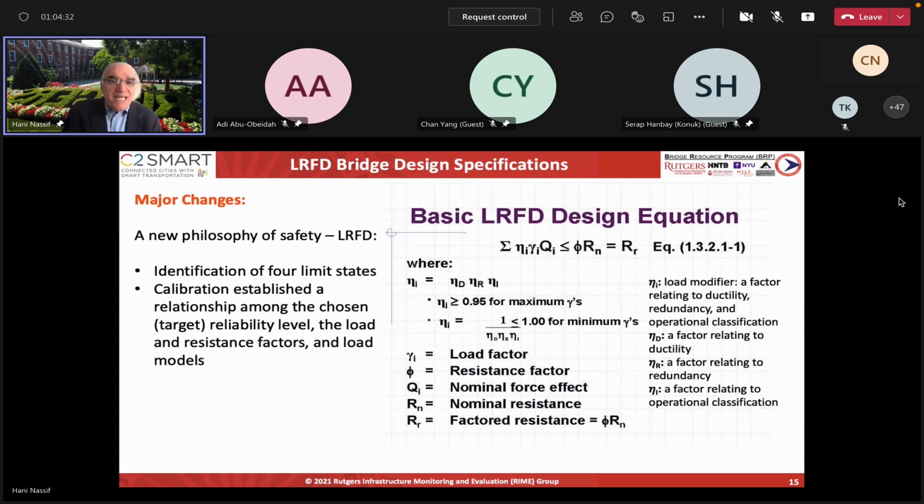Therefore, you have to penalize that and make the loads even higher, because you don't know if they will fall within that range. Whereas dead load, you can measure it. Even though you ask for, let's say, a 12-inch web, you might get a 13-inch web because the form might bulge, so there is a little bit of increase in that, but not the variability. It's still more controlled, and that's why you have a lower factor. So the load factors are trying to accommodate the uncertainty in estimating the loads.